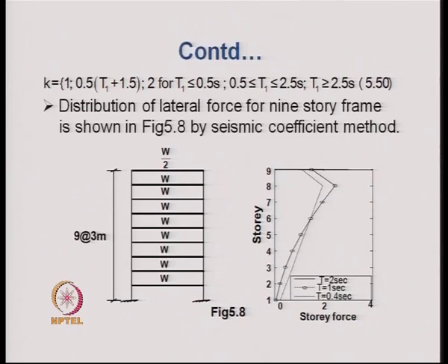The figure shows that the variation of the story forces, that is the forces distributed along the height of the building, varies non-linearly for time period equal to 1 second, for time period equal to 0.4 second and 2 seconds. These variations are mildly non-linear.